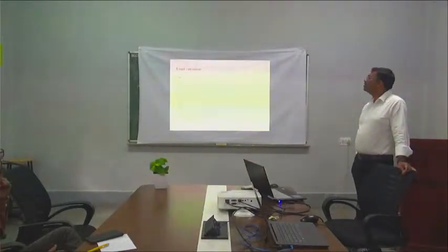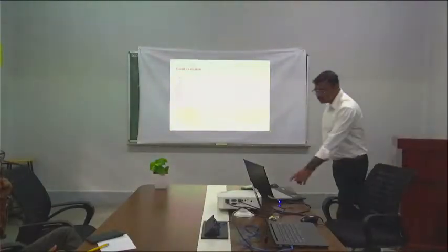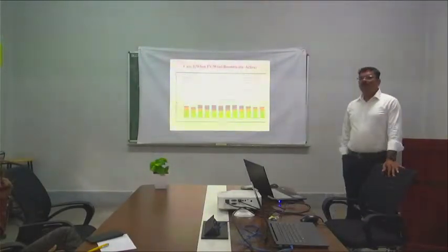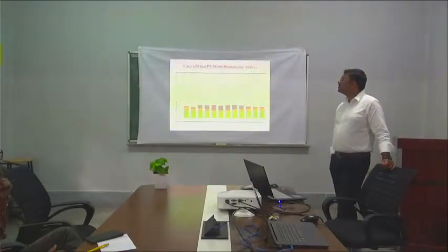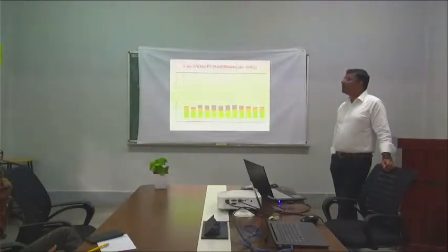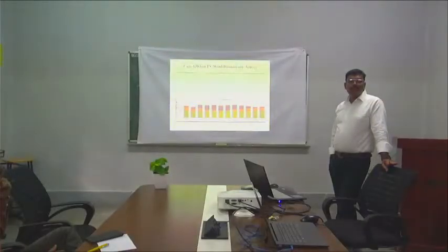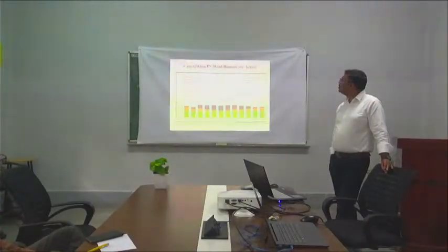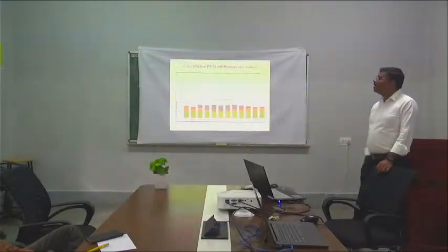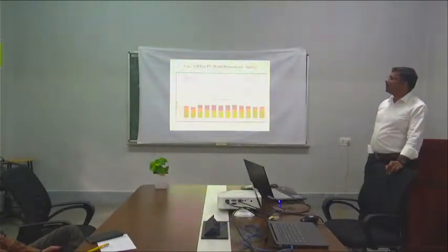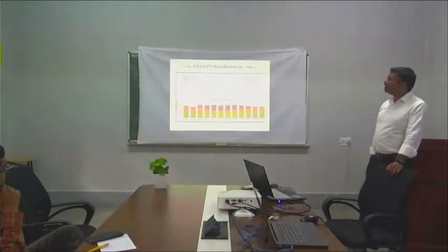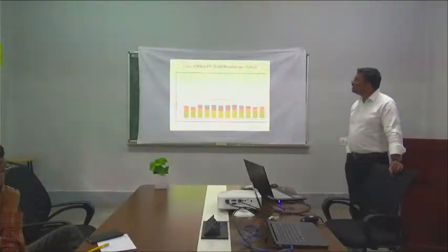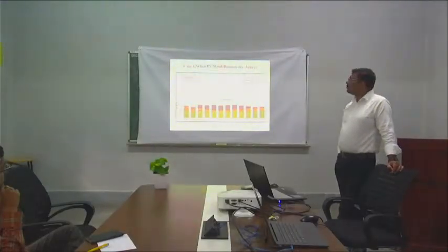I want to meet this load from this particular system. Now when I simulate, the reports I generate for the first case are when PV, wind and biomass are active. PV is available, biomass is available and wind is available. This is in kilowatt hours per year. How much energy is generated from the solar photovoltaic system? Some 65,539 kilowatt hours is generated from the solar PV system.